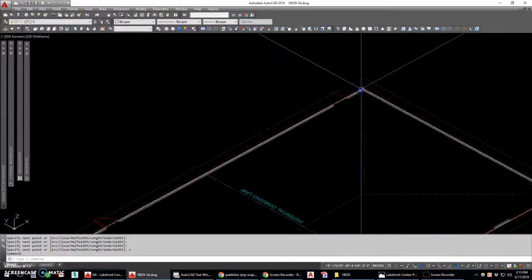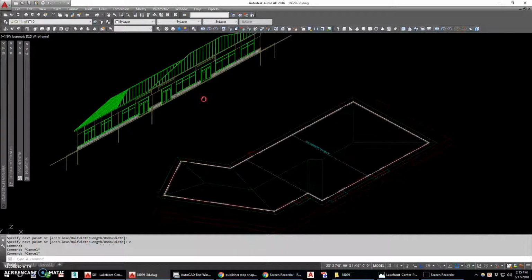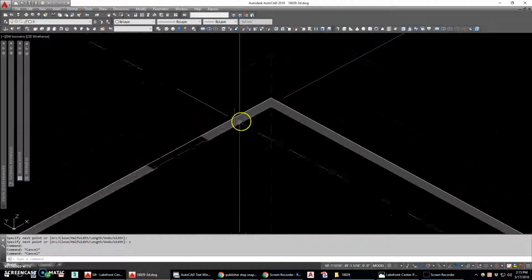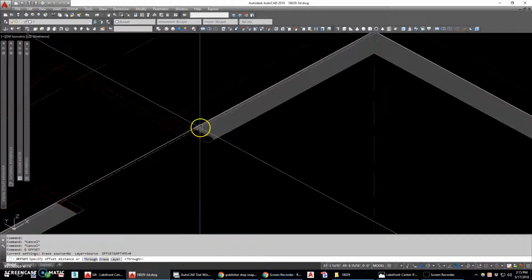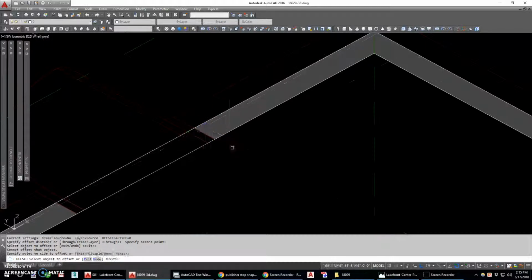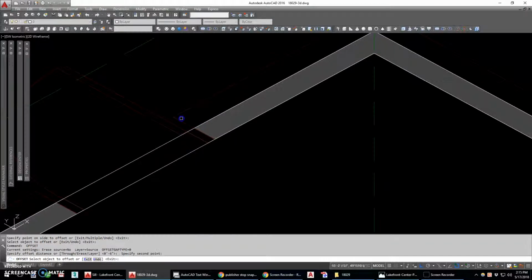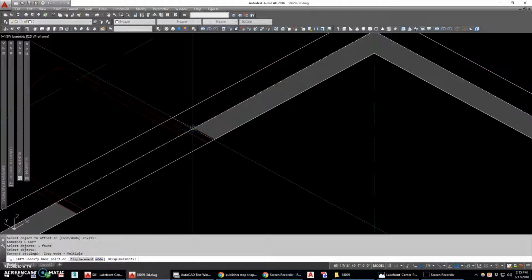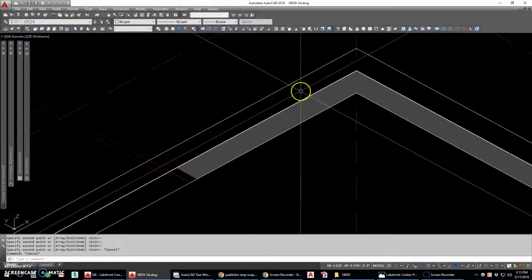And now this one polyline, so I drew a closed polyline around the building. We're going to derive everything from that. I drew it on the exterior of the wall, not the brick itself. But I'm going to offset that line to the thickness of the wall. I'm going to offset that line the thickness of the brick, and then I'm actually going to copy this original line over itself a couple times because I might need that again. So I just made 4 or 5 copies.